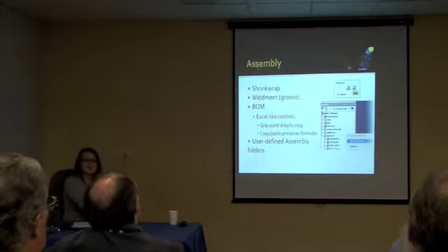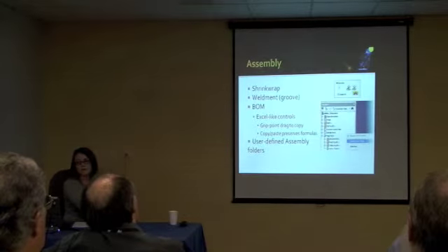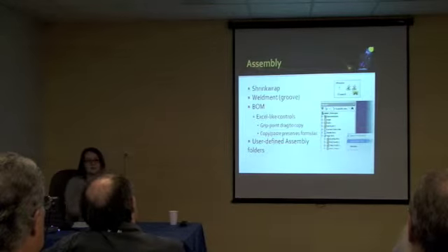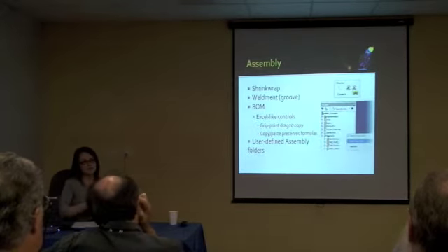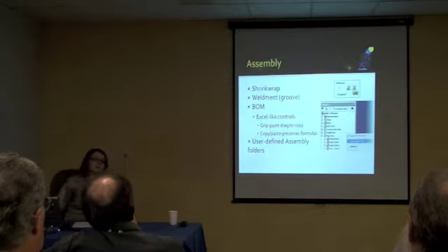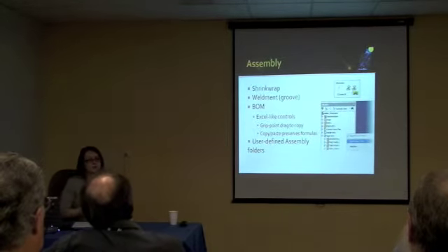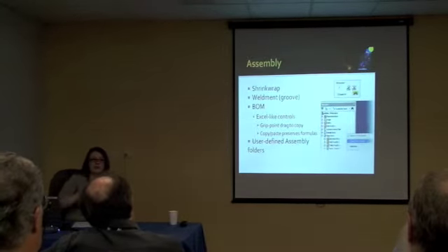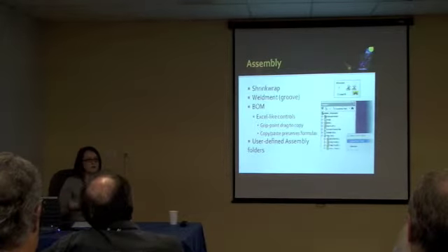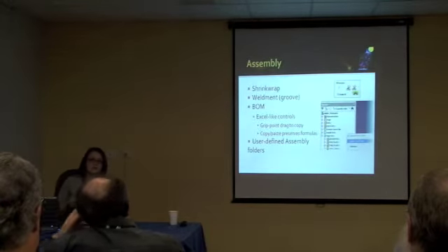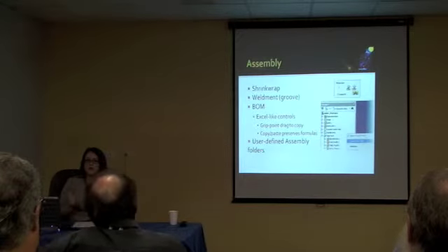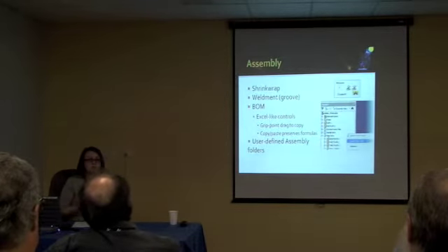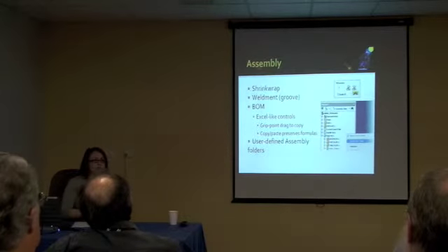Assembly mode, not too many enhancements, but one vital one, I think, called shrink wrap, which enables you to automate a task that some of us may have been doing in the past, where you get a request to send an assembly to a third party that you don't want to share all of your data with. In the past, we would probably take that assembly, create a derived part from it, and break the link. Shrink wrap automates all that. But it also has some additional options, and it lets you fill any holes that are between a minimum or maximum range. So you can exclude information based on part size or hole size or a whole bunch of different options.